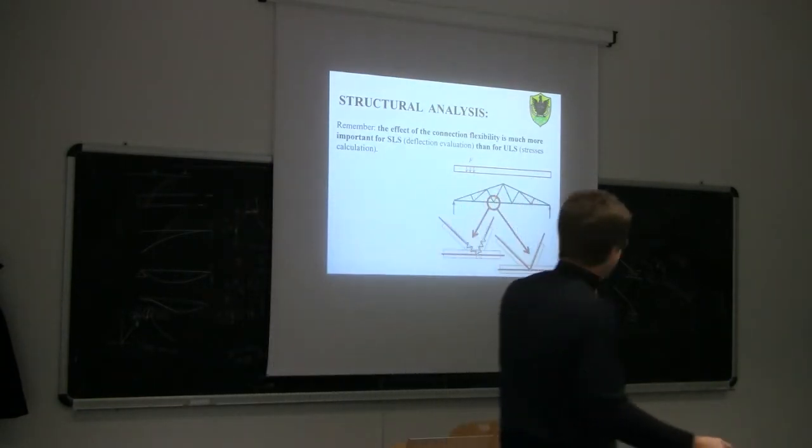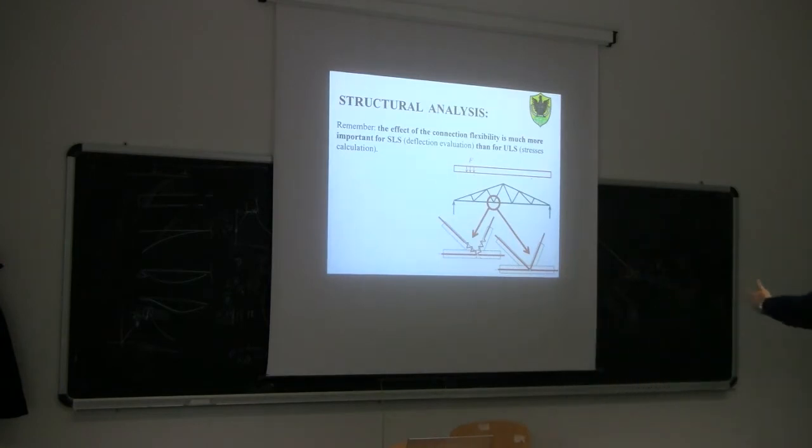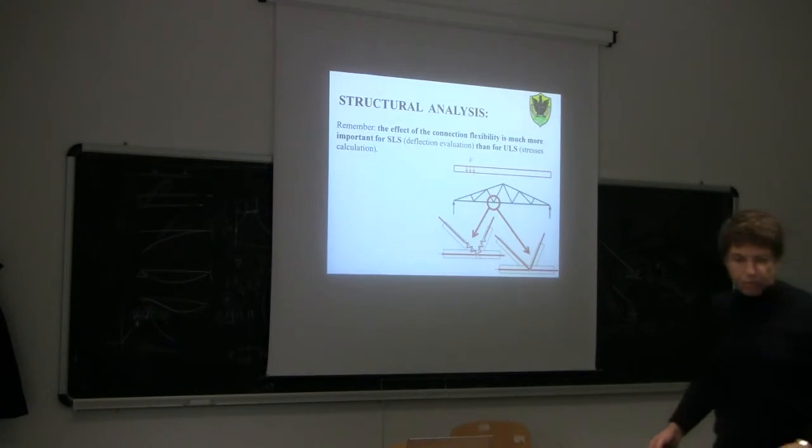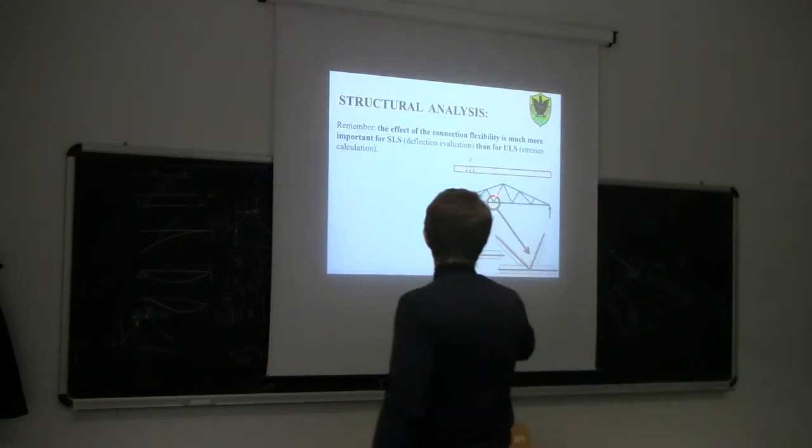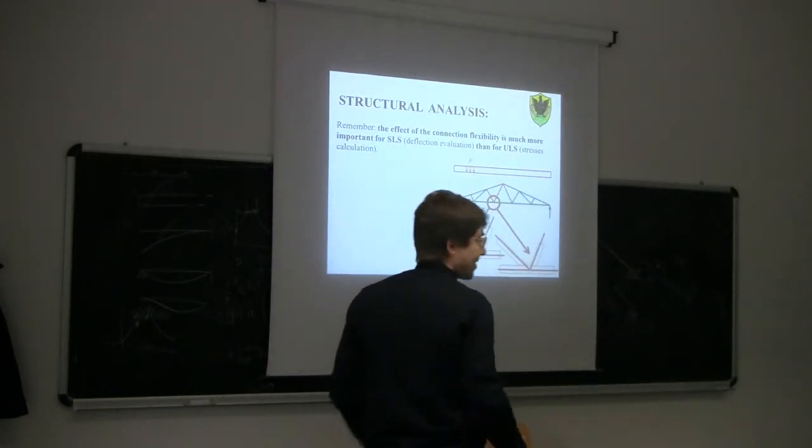SAP2000. Obviously, with SAP2000 it's not a big problem, because with SAP2000 you can schematize the whole system quite simply. Then you need to go in all of these joints, and then you need to use the end release function. Because by default, SAP2000 would basically consider all those joints as rigid.